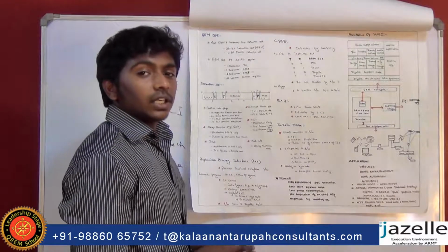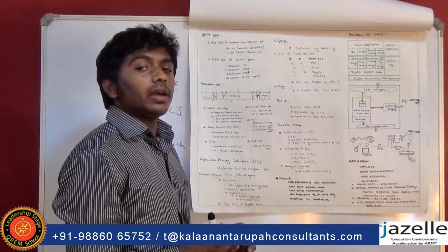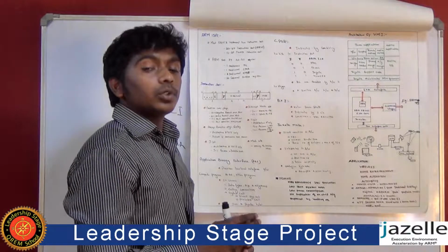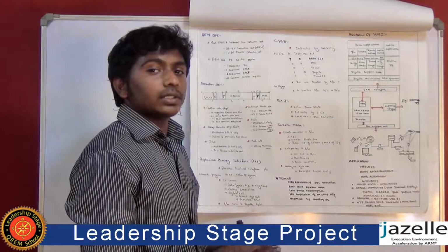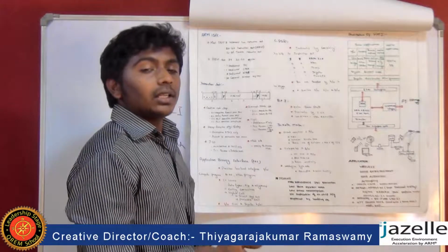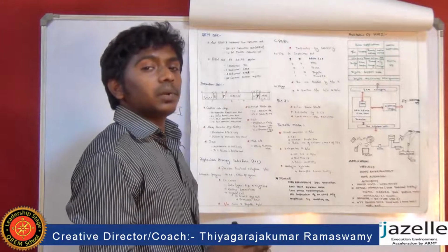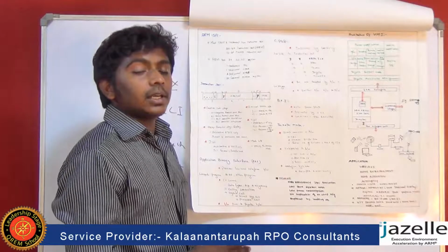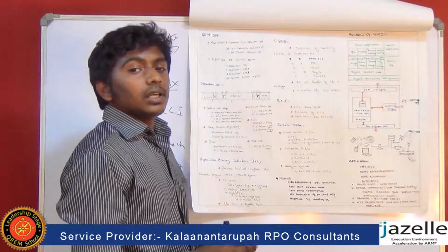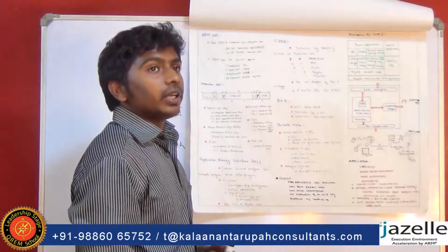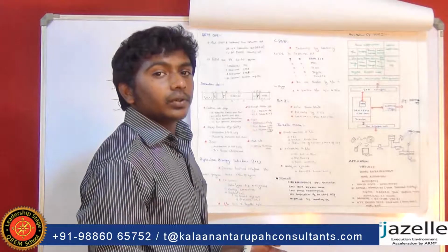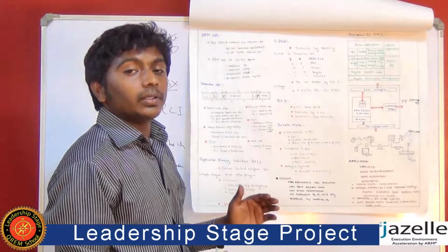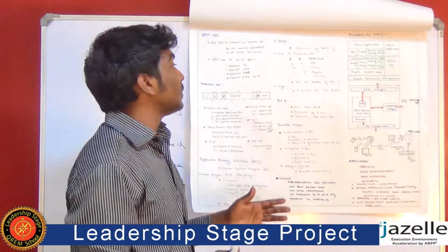The first one is the 32-bit ARM instruction set, and it is mostly used for executing normal instructions. The second one is the 16-bit Thumb instruction set, and the third one is the 8-bit Jazelle instruction set, and it is used for the compilation of Jazelle bytecode, Java bytecode, to machine code.